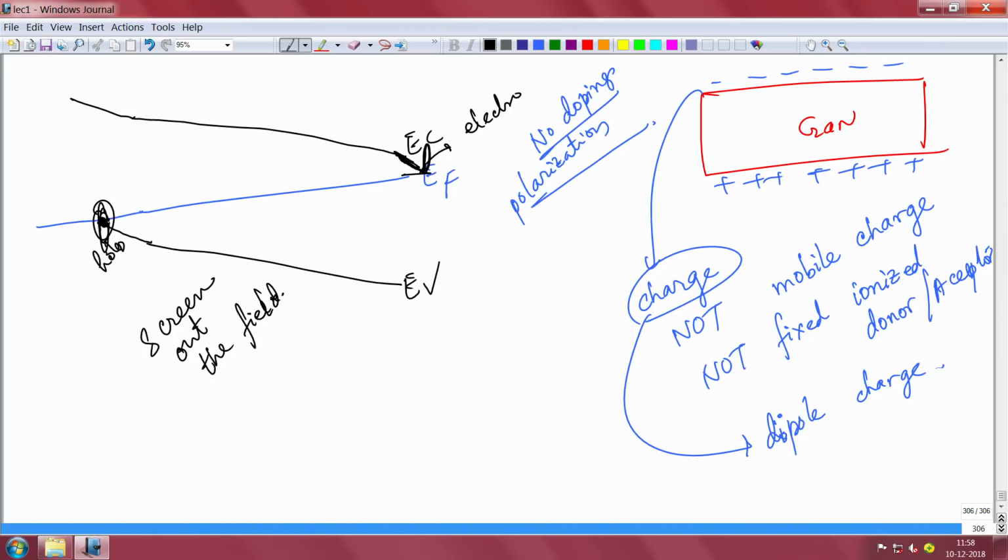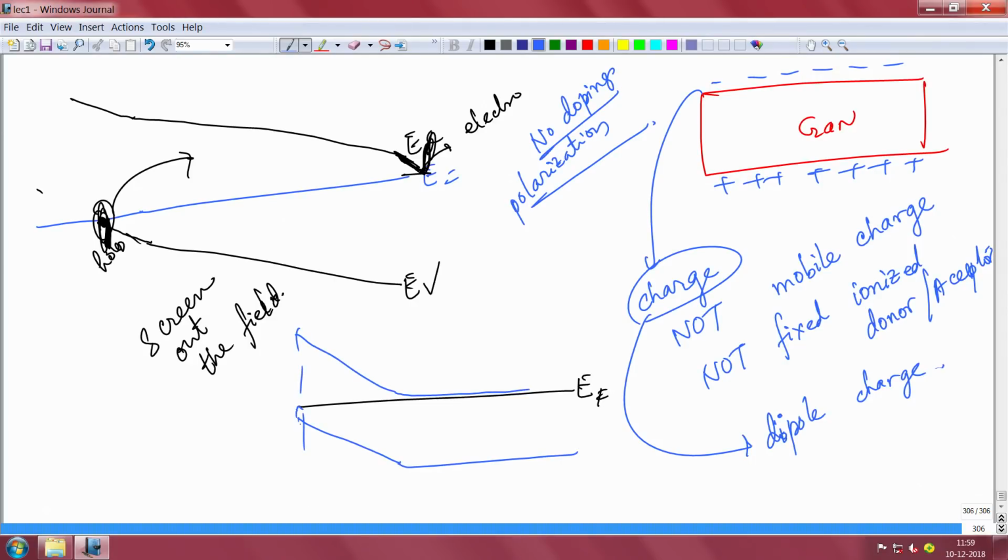So you cannot keep growing it; this valence band cannot go like that. Okay, that is not possible. It will get pinned here because you will get a very large density of holes and electrons that will essentially screen out the field. So eventually this is your Fermi level, and after that it will go like this, with the entire band gap dropping here. Only up to a certain thickness will you have that field, that is a critical thickness, T critical, and for gallium nitride probably that is around 20 nanometers or so, if I recall correctly, or maybe even less.